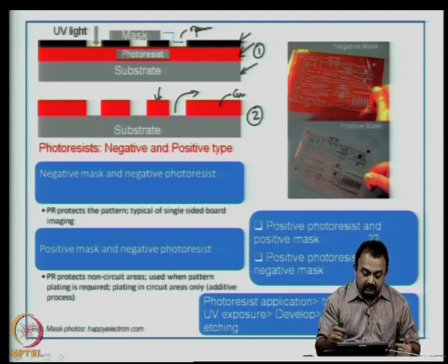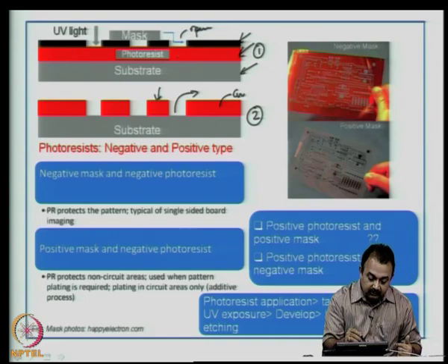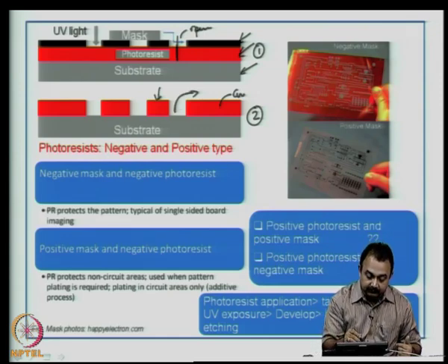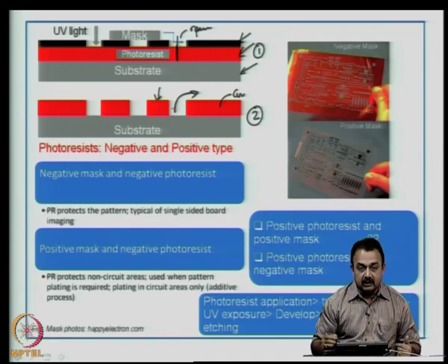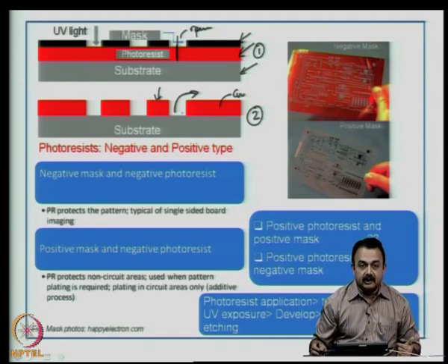So, you can see here those areas in this particular diagram, specifically those areas which were exposed to UV light, that is the photoresist in these areas which was exposed to UV light has been washed away, right. That is the understanding here. So, those areas which were masked and protected by the UV light has still been found on the substrate without any areas getting affected.